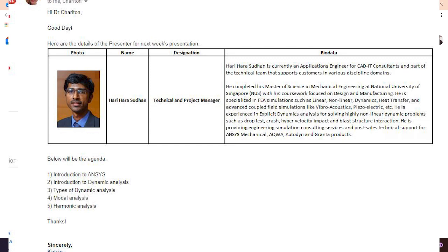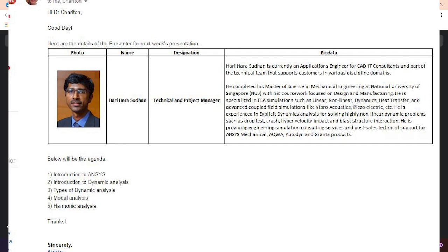There is a need to define the interaction between the bodies. Contacts is one of the ways to define the interaction between the bodies in the simulation. One of the advantages here is that in ANSYS we have an automatic method to detect the contact regions. When you import the CAD model into ANSYS, the program will automatically detect all the contact interfaces and create a contact region.